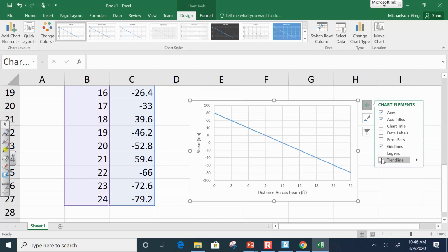I hope. Okay? So that's what our shear diagram looks like, but let's be clear. That is the diagram representing the loads, okay? The force on the beam, okay? Now, one of the things that you'll find from a shear perspective, we've got positive shears and negative shears. What does that physically actually mean when I say positive versus negative shears? Well, it means, am I shearing the beam this way, or am I shearing it this way? Now, does that really matter in terms of how the beam performs? Not really.